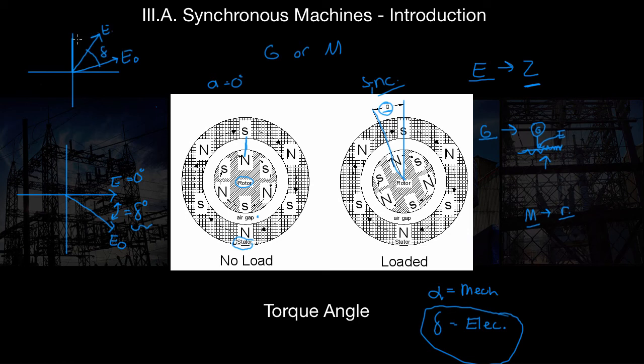And remember, since vectors, they're constantly rotating at all times. So anytime we draw a phasor diagram, we're looking at a snapshot. We're looking at when a time equals a specific value. So typically what we do is we always put our voltage value on the x-axis for reference, because it gives us a better intuitive standing, patterns emerge, it's easier to tell if things are leading or lagging, etc.